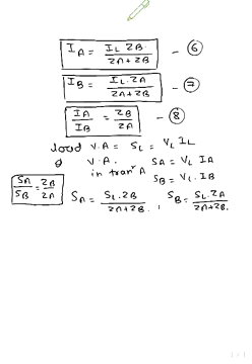If we multiply the load voltage by each transformer's current, we find the VA. The load volt-ampere we represent as SL, which is equal to VL into IL. Similarly, the VA of transformer A is SA equal to VL into IA, and SB for transformer B is equal to VL into IB.